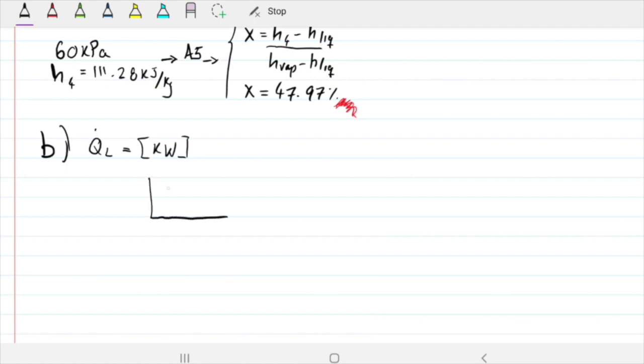Because what we have on the condenser is the following. Let's do it in green. We have water coming in at 18 Celsius and leaving at 26 Celsius. At the same time, we have 134a coming in at 65, and obviously decreasing because we can't create energy, so it decreases to, what is it, 42.